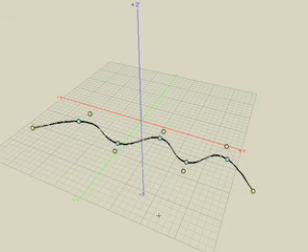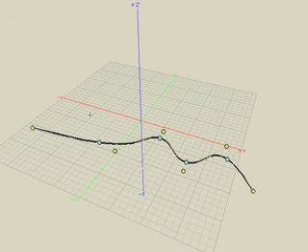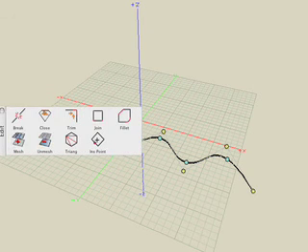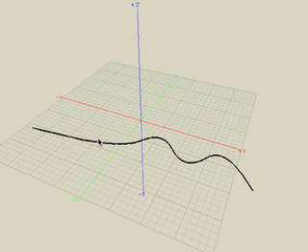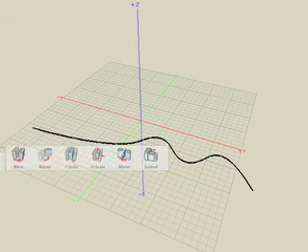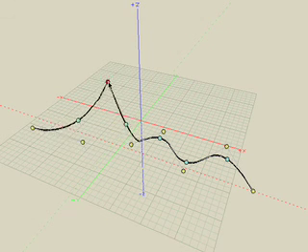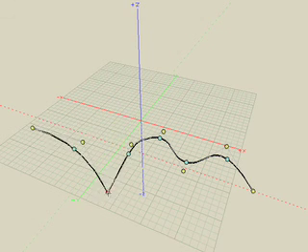It should be noted that you can delete control points using the Delete tool. Simply click on the control, and the control is deleted from the curve. You can also break the continuity of the curve by inserting a point into the curve itself. This is not adding controls or inserting controls into the curve. It's inserting a physical point into the curve itself. So if we were to move some of those controls, you can see we now have a sharp corner point at the position of that one continuous curve.